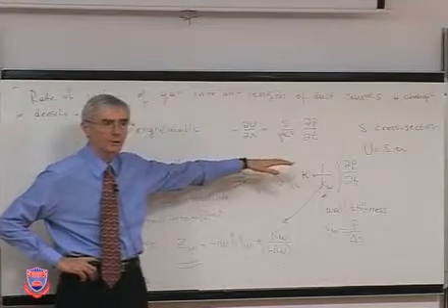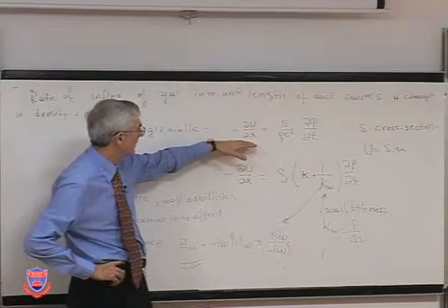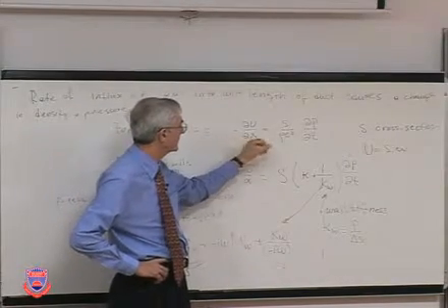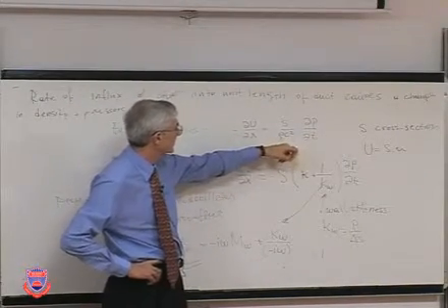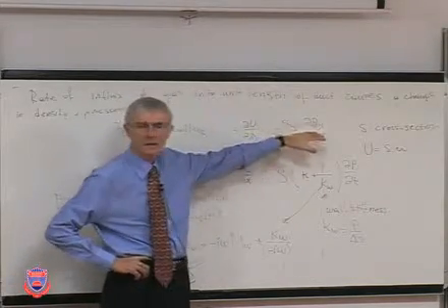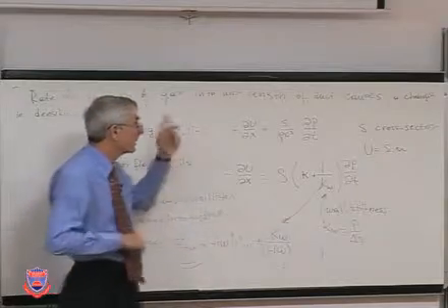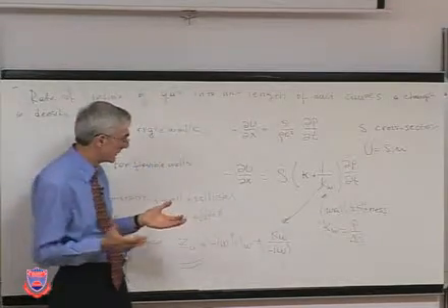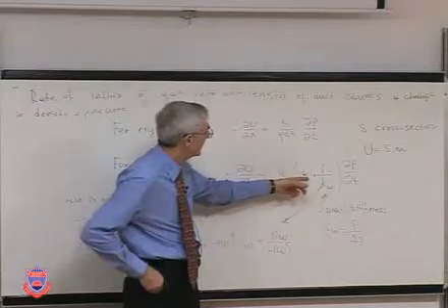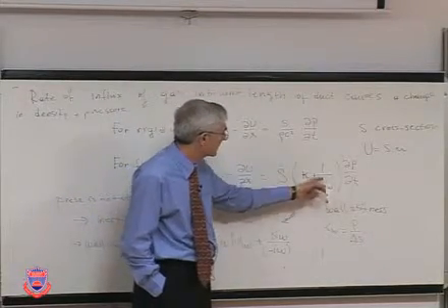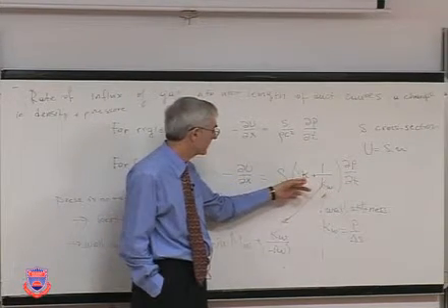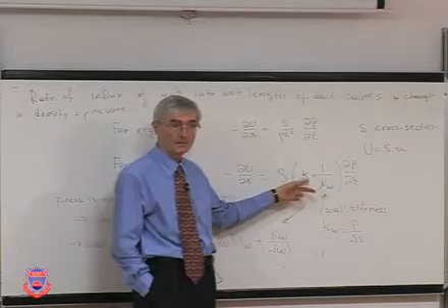When the walls are rigid, as before, the relationship with the flow gradient and pressure fluctuation with respect to time is very simple, given by a constant cross-sectional area. But now cross-sectional area is not constant, okay? So it has some sort of stiffness. If that's the case, that stiffness, or this is the admittance, inverse of the stiffness, you add it to the compressibility.